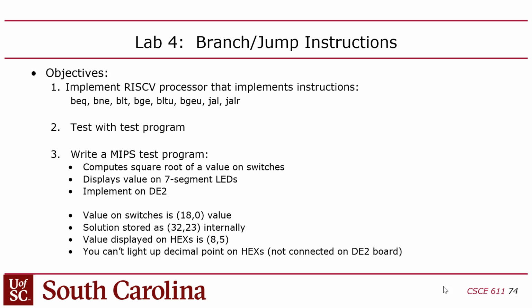So the way to do it is to treat the decimal hex displays as a fixed point where the first 3 digits are whole digits. And when I say digits, I really mean digits, base 10 digits. And the other 5 are fractional, right? Why? Because if you take all the switches and push them up, that's going to give you an input value of 262,143, I believe. And the square root of that is like 511.9999999, right? So the maximum output is going to be just under 512, which means we only need 3 whole numbers followed by 5 fractional numbers. Does that make sense?